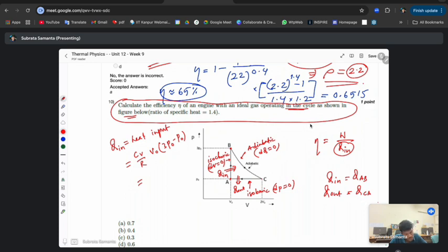So then how to calculate this? So Cv over R, and then the PV, right? So this is basically 2 P naught V, and your Cv is basically R over gamma minus 1, right? So it's the constant volume Cv, because the heat enters through the A to B process, which is constant volume, so Cv is R over gamma minus 1. So that is your Q in.